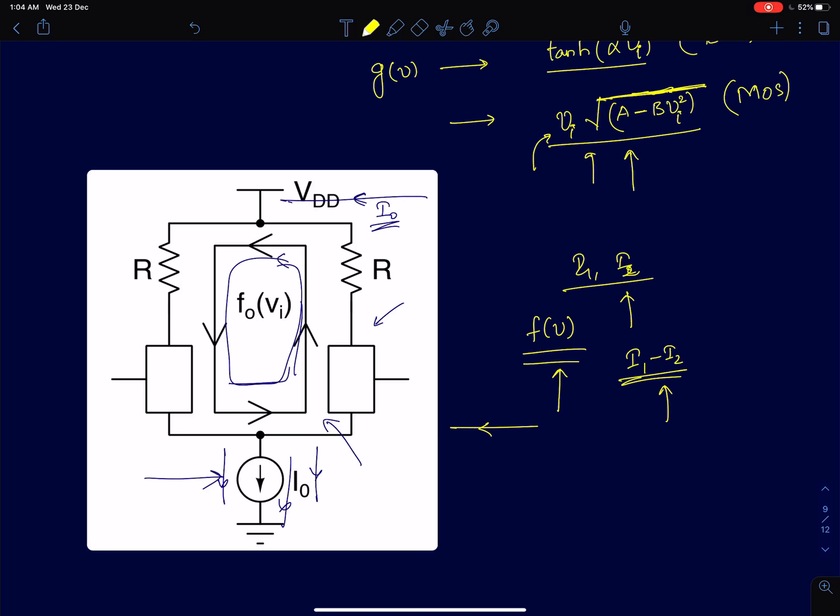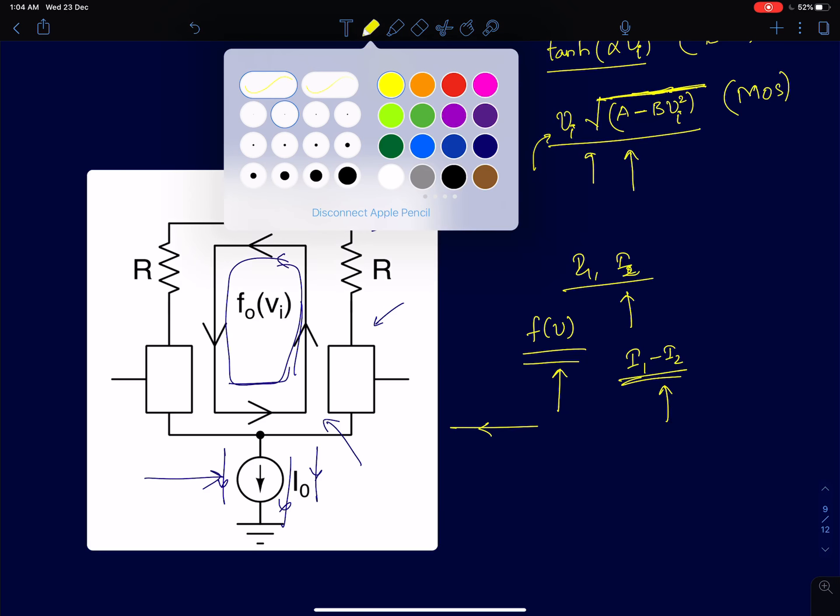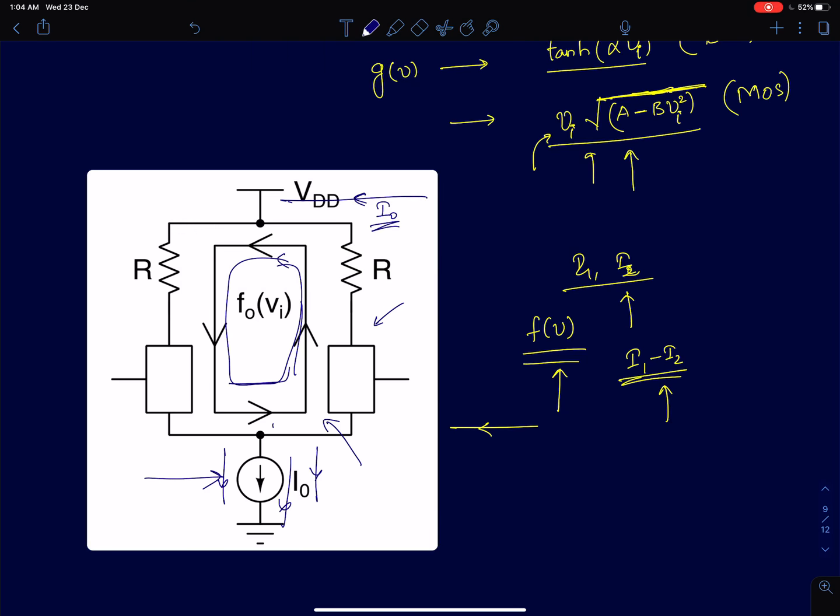The circuit itself obliterates any even harmonic component that's present in the circuit. And how does it do that? We just intuitively said that the source voltage here can move. The source voltage here can actually change. The source voltage will change in a nonlinear way so that the currents flowing in these two devices will only be odd harmonics of the input frequency.